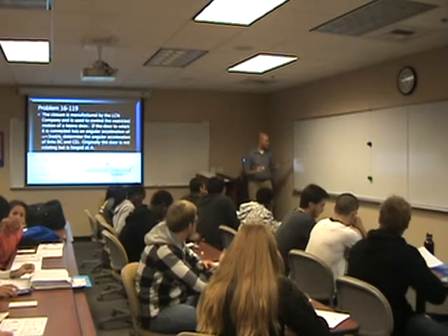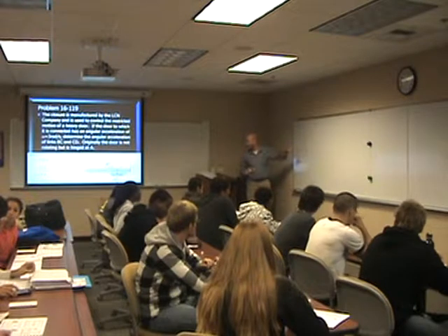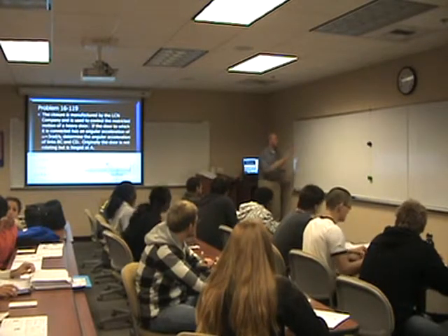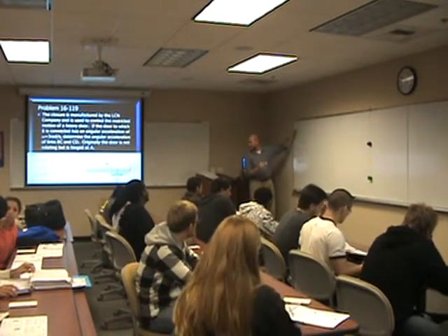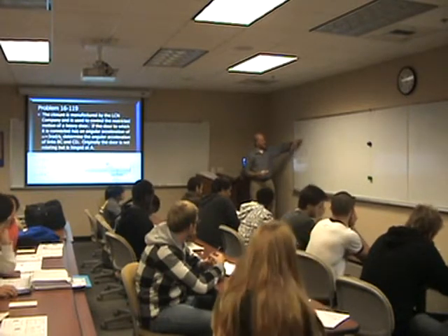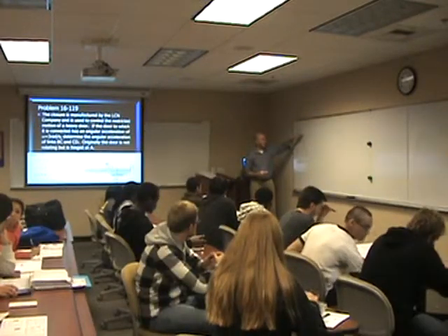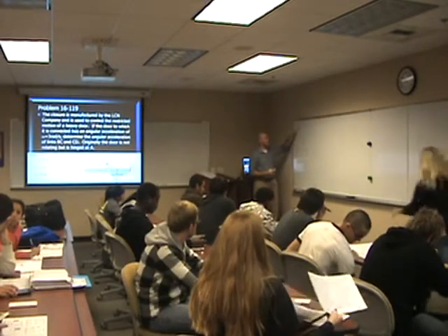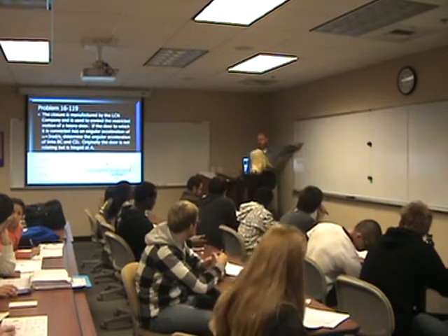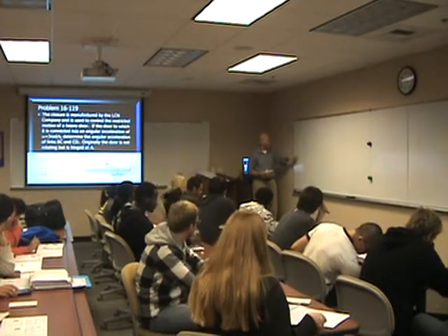So our basic equation is the acceleration of C equals the acceleration of B plus the acceleration of C with respect to B. Acceleration of C is on link DC, and so whenever we have something on a link, we're going to have a normal and tangential component.